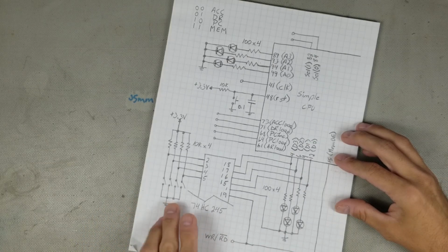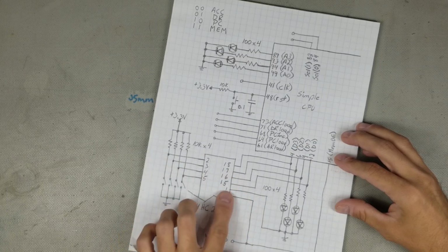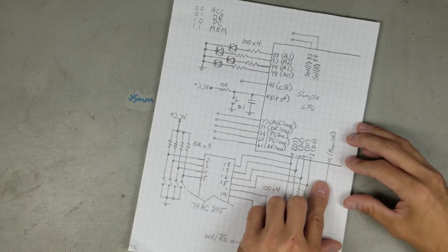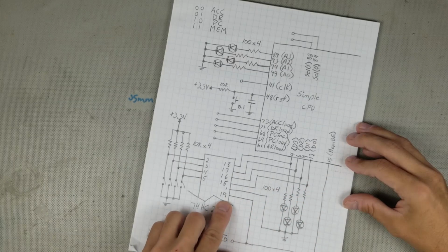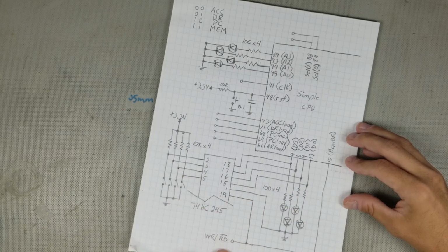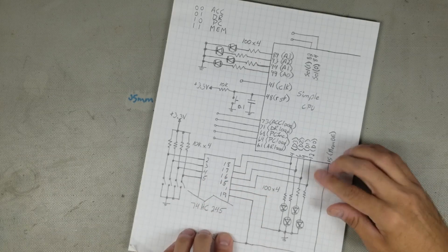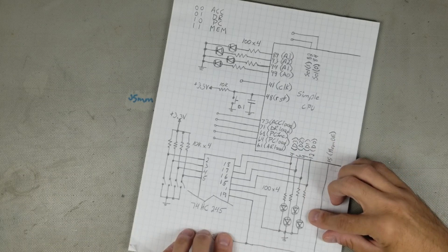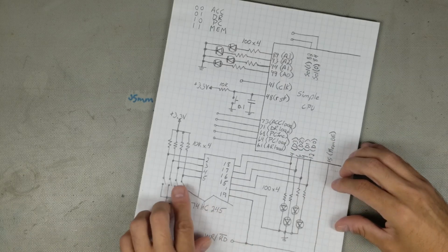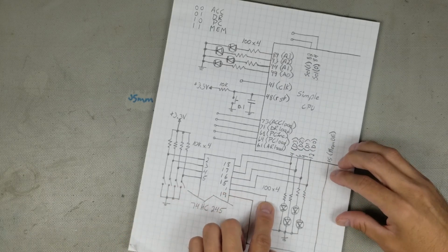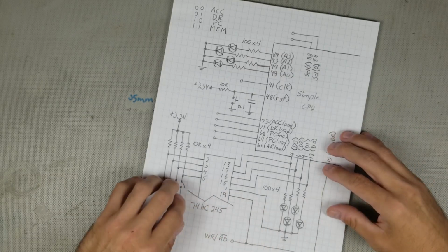Since the transceiver only puts data onto the bus, the direction pin is tied low. To control the data flow in the data bus, the memory output enable is tied to the enable pin of the 245, which will be controlled by another wire just like the control lines. So when the read-write line is high, whatever is on the internal data bus will be shown on the LEDs. And when it is low, the value of the dip switches will be placed on the memory bus and shown on the LEDs. With that out of the way, let's wire it up.